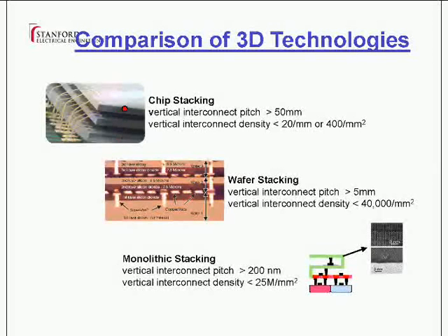This allows us to increase the device density without any significant improvement in technology. All it needs is more sophisticated packaging or bonding technologies. Stacking multiple wafers is already close to production. In fact, some foundries have already announced that they will be providing this type of service towards the end of this year. Of course, the ultimate goal here is to allow us to monolithically stack transistors right on top of metals. This is an area where we're conducting advanced research.